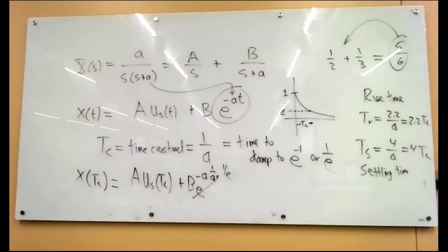Okay, if you remember, some modes turn out to be second order instead of first order. So we'll review that next time on second order systems and how we characterize those. You probably heard, right, damping ratio and natural frequency. So those are the things that you go then look up in the FAA regs and figure out whether your airplane behaves properly or not.